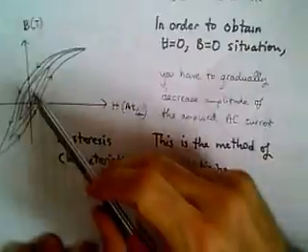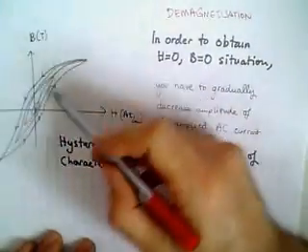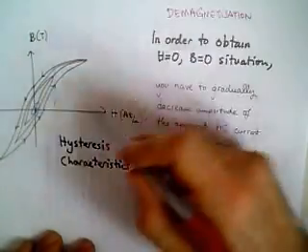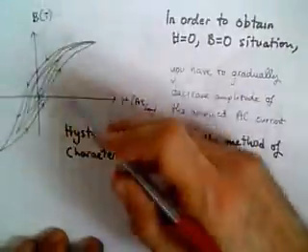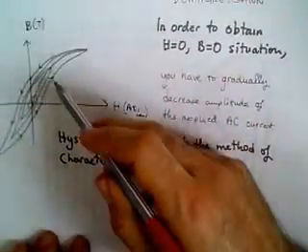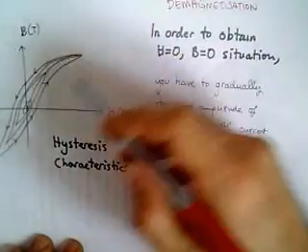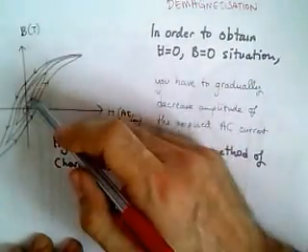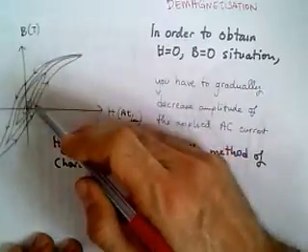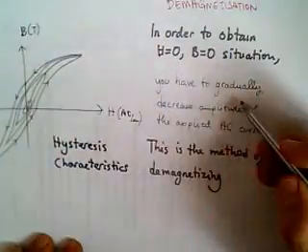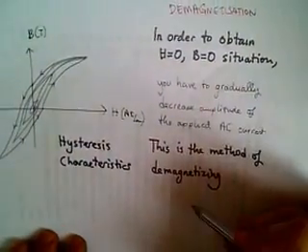If we have some material which is magnetic, we can demagnetize it by using this trick, gradually decreasing the amplitude of the AC current of the magnetic circuit which holds that material. So gradually decrease the amplitude.